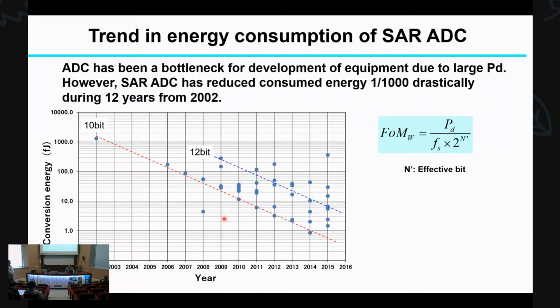But in combination, even though you use a 10-bit ADC, you can realize effectively 14-bit by using a variable gain amplifier or some delta sigma processing method. But basically, high resolution and high speed ADCs consume much power. That is the nature.